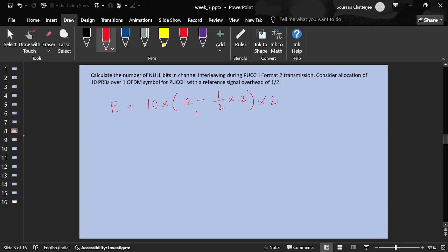And when I have both uplink data and control information to transmit, I am going to multiplex them both, and essentially PUCCH won't exist, it's only PUSCH, right? And then only I am going to use the higher modulation scheme. And when I say multiplexing is happening, at what stage will it happen? The rate matching. Okay, at the rate matching stage you will do the control and data multiplexing.